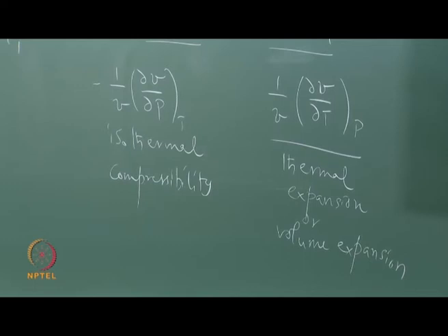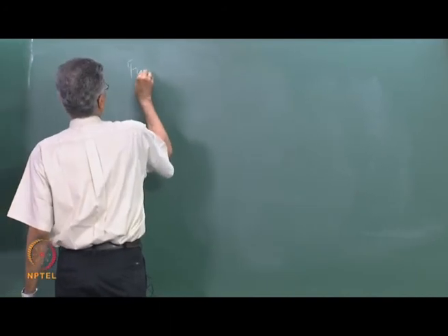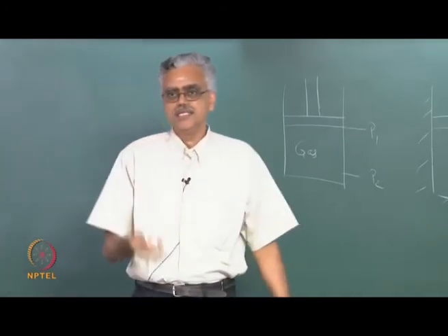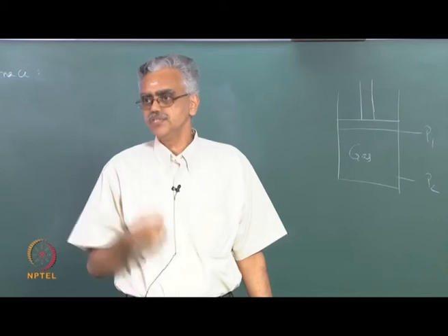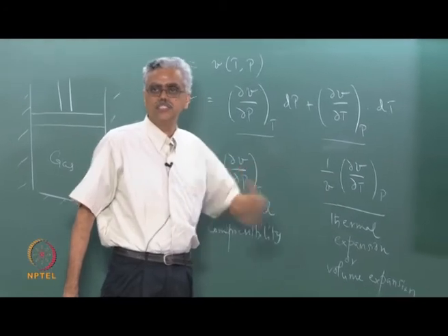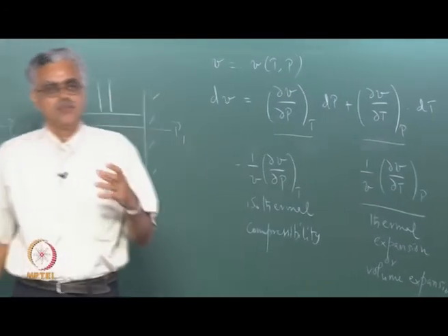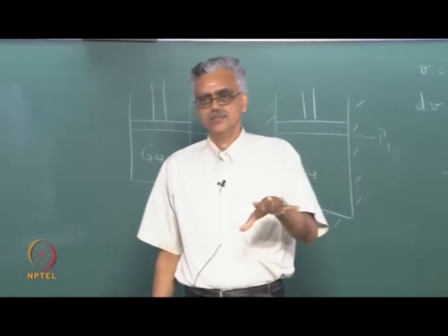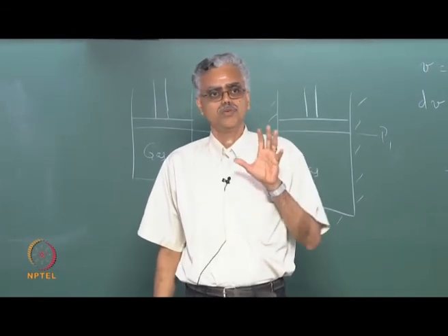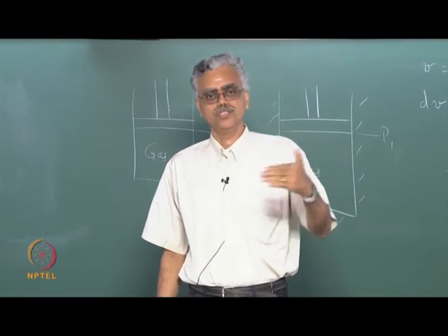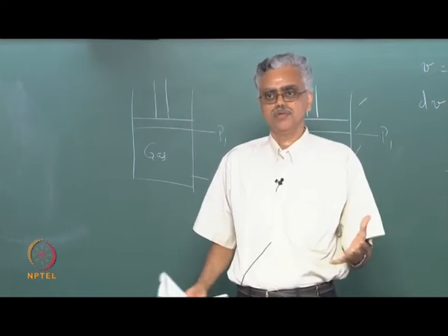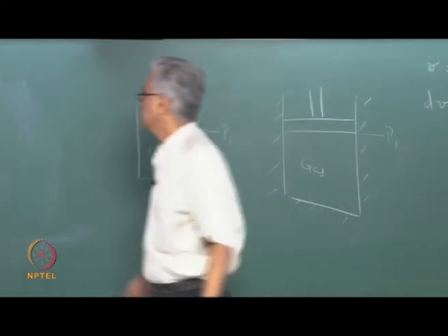If I think about, let us say, a large furnace or combustion chamber, you know that the change in temperature is very large, and so the change in specific volume is also going to be quite large. So the change in specific volume due to the change in temperature is very large. But the question is, is the flow inside a furnace compressible or not? Is the compressibility effect important inside the furnace or not? What about the pressure inside the furnace or combustion chamber? Does it also change or does it remain more or less constant? The furnace can actually operate at atmospheric pressure, but it can have large changes in temperature and specific volume.